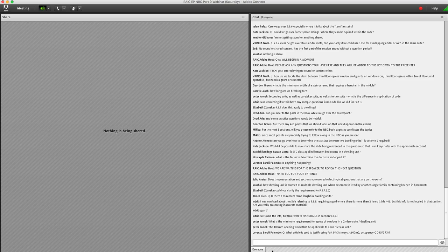So I think for this question, the flame spread rating discussion was mainly on the duct linings and duct outer coverings. And just in general, where you may be looking at this in terms of other areas, other than the mechanical portion of the code, flame spread ratings are published based on the materials.